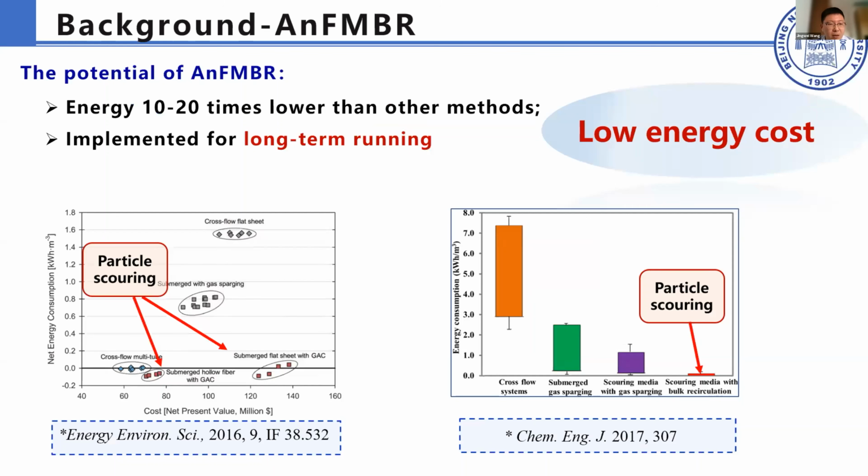Many papers have compared the fouling control methods in terms of energy consumption. As you can see from these figures, particle scouring always achieved very low energy consumption, especially when coupled with the submerged membrane module. So the energy consumption is very low.